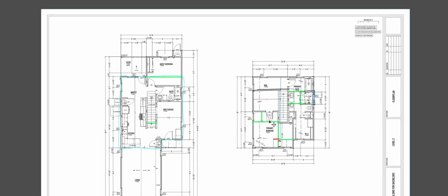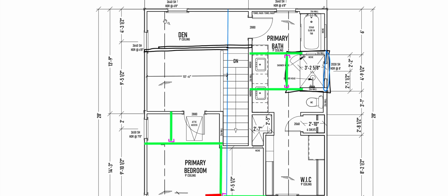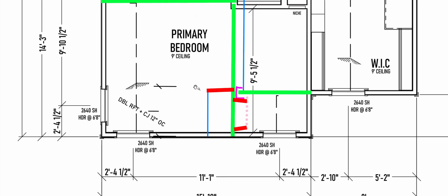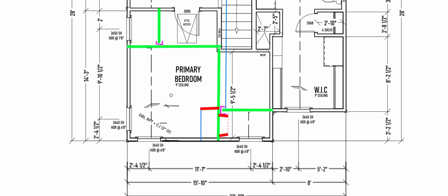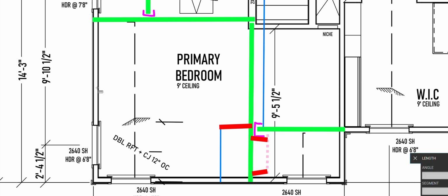So let's go back up to the plan. Let's take a look. Now we know from the back wall all the way to this spot right here is the same framing except for this dormer. We've got this rafter thing going on with the ceiling joist except for this dormer. It's flat ceiling here. So from the wall in, because I've got nothing to support over here, I want to take my span from this side.